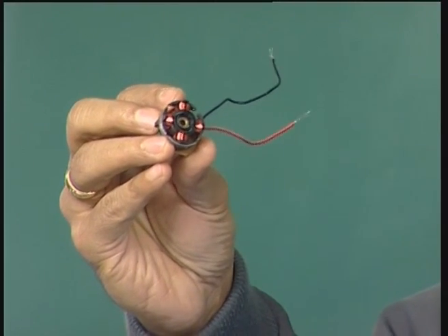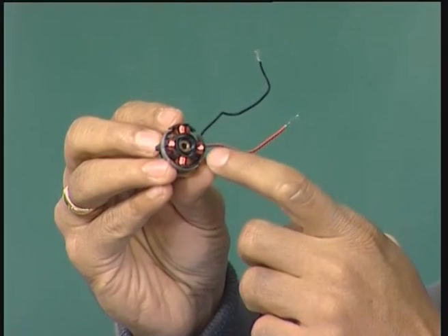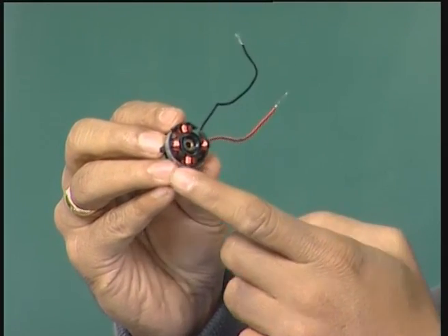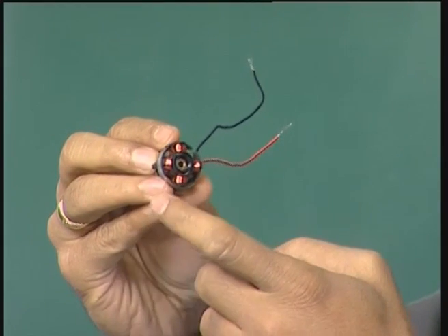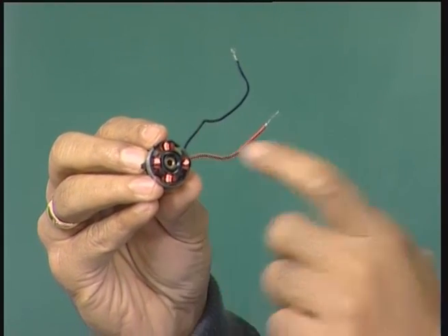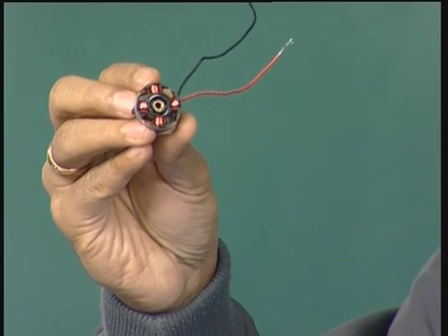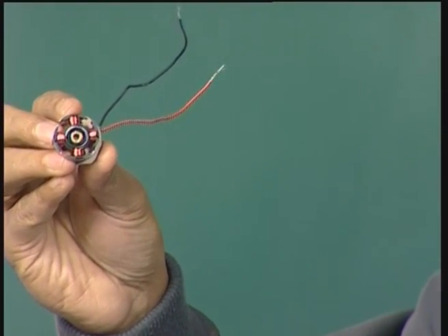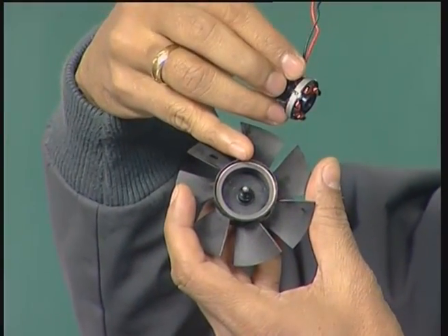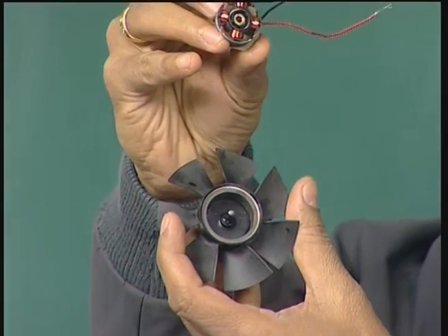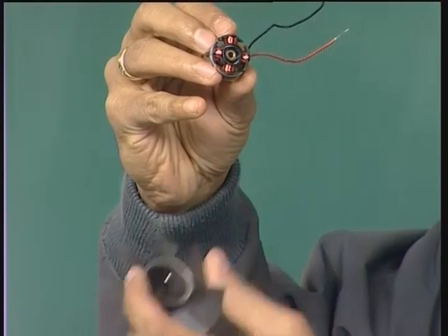You can see here that we have all these windings, the copper windings are placed here, and here. For example, here we have 4 windings, 1, 2, 3 and 4, and these windings have to be excited depending upon the rotor position. The rotor is a magnet, the magnets are arranged inside this, and this is the stator which is inside, and the rotor is free to rotate.